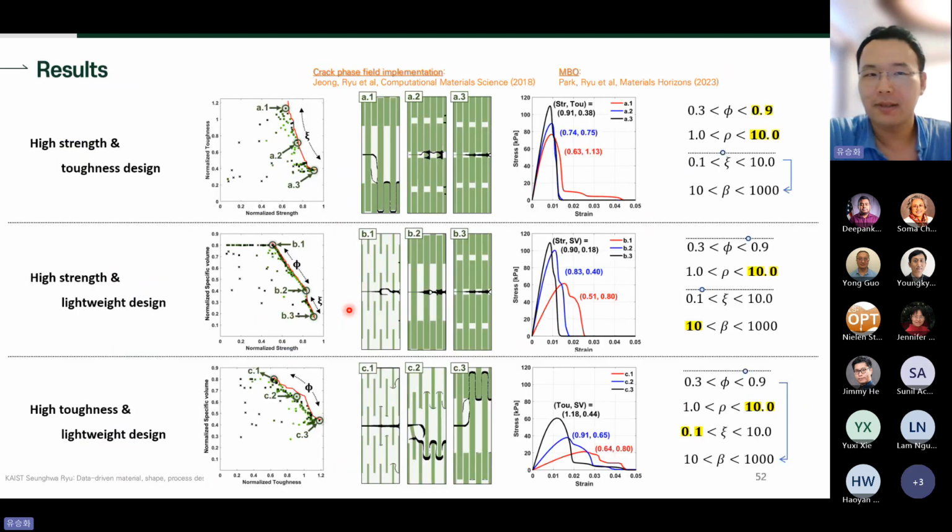So yeah, the example is as follows. In terms of the strength and toughness trade-off relationship and Pareto optimum search, Abacus keeps generating the data set, more than 100 data points, to find this Pareto optimum. And if we search for the designs along this Pareto optimum, we see what we need to change to tune the strength and toughness within the Pareto optimum, because we cannot optimize strength and toughness together. We cannot achieve it that way. However, within the Pareto optimum, at least this kind of simulation suggests to us what the critical design variables are.